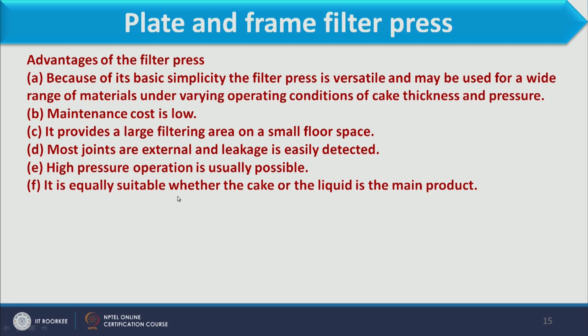It is equally suitable whether the cake or the liquid is the main product, because here solid is deposited as cake and that cake we remove very effectively. So if solid is the purpose, that we can also obtain. And because the complete structure is so compact, the complete assembly is tightly pressed, therefore whatever cake we have obtained contains less moisture. So that is another advantage of this.